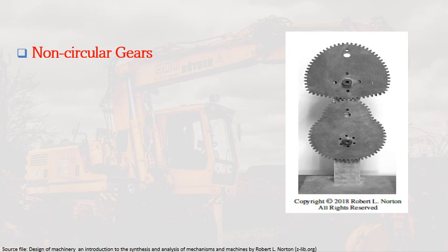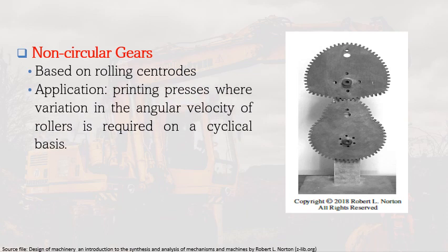Then we have non-circular gears. They are based on rolling centroids. They are applied, for example, on printing presses where variation in the angular velocity of the roller is required on a cyclical basis.